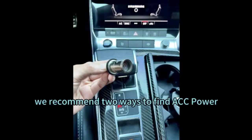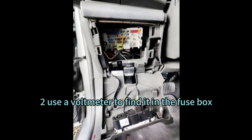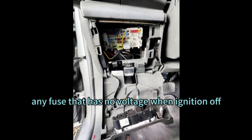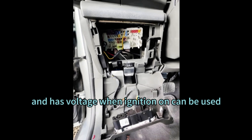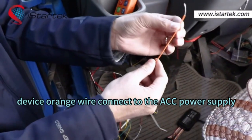We recommend two ways to find ACC power supply. 1. Cigarette lighter. The power supply of the cigarette lighter is ACC power supply. 2. Use a voltmeter to find it in the fuse box. Most of the fuses are ACC power supplies. Any fuse that has no voltage when ignition is off, and has voltage when ignition is on can be used. Device orange wire, connect to the ACC power supply.